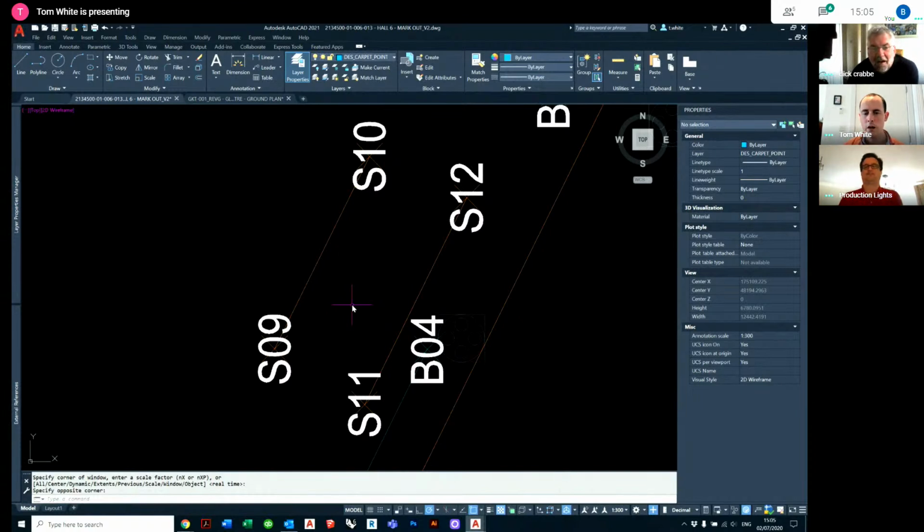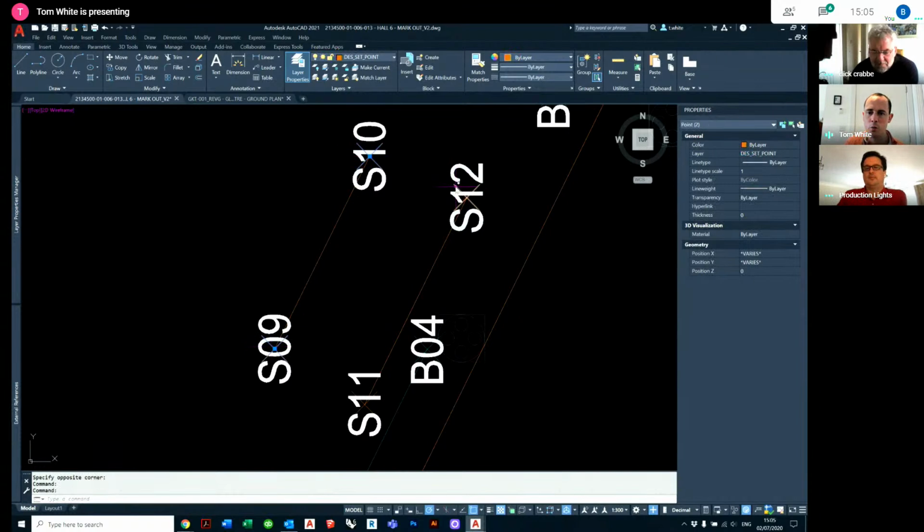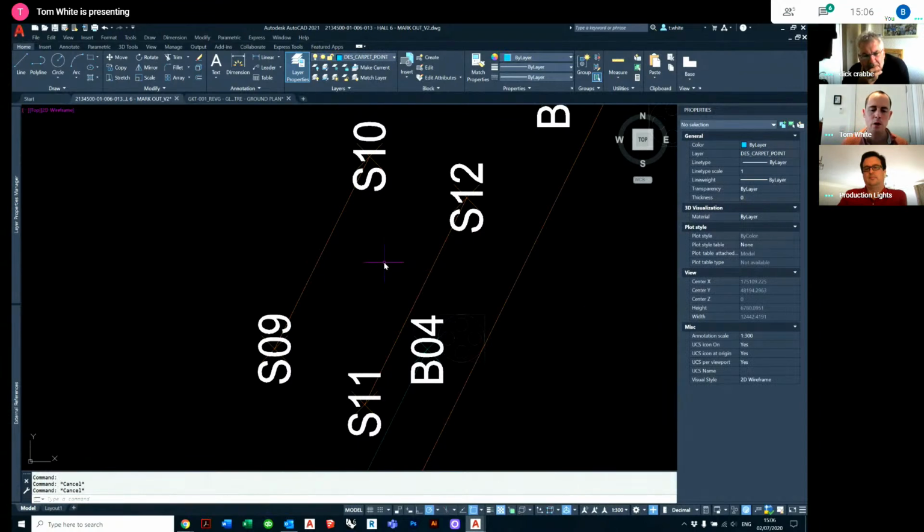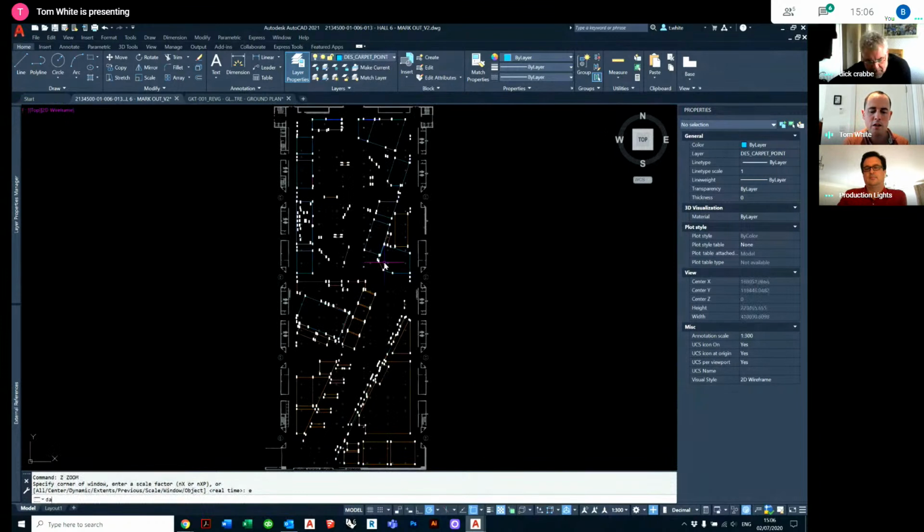So, yeah. The example I'm going to present now is I would like to have the points, this point here, and this point here, and this point here, and this point here, written in a numerical way, rather than me clicking on this and saying, oh, it's position 175497, I would desire to do it automatically. So I'm going to do Z, enter, E, enter to zoom extents, and I'm going to write in data extraction. I'm not going to spell the whole thing.